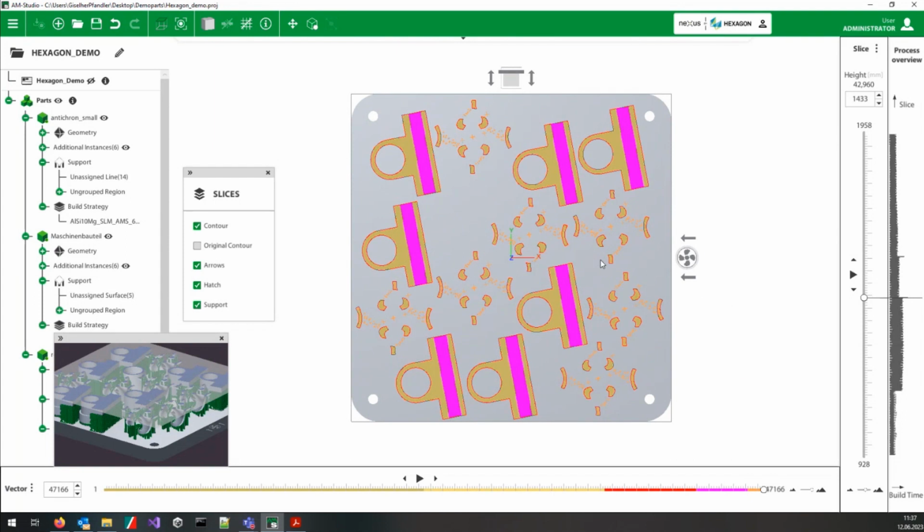So that the layer is lasered twice, and that's why we have a lot more time for this layer. And so you can use the graph to see what's happening during the build process, if there are some jumps within. So you can also imagine the more time you take for the layer, the more energy is brought into the layer. You want to have a smooth shape of this curve, so there should be similar energy entries per layer.